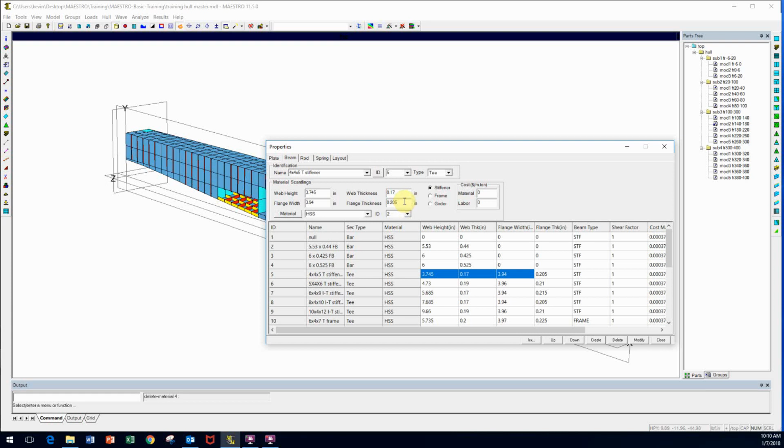All these are out of the catalogs. You define whether or not this is a stiffener, a frame, or a girder. This becomes important if you go to a more fine mesh model called level 2, where stiffeners are modeled explicitly. At that point, Maestro needs to know, is this a stiffener or a frame for failure modes as it assembles what are called the evaluation patches.